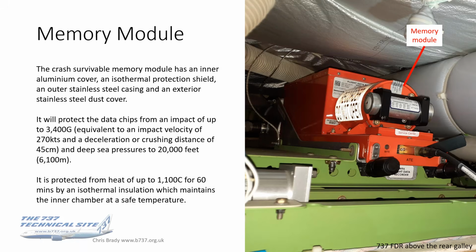Okay, so let's take a closer look at the heart of it, which is the memory module. This is crash survivable. It's got an inner aluminium cover, an isothermal protection shield, and an outer stainless steel casing, and a further exterior stainless steel dust cover. So it's extremely robust.